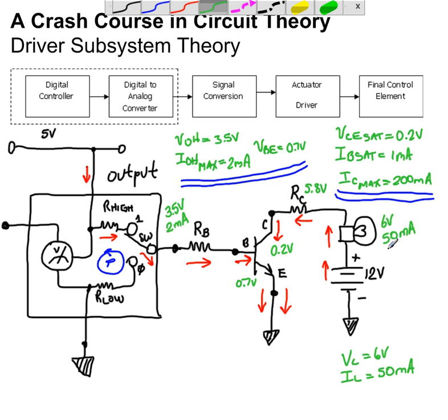Since we desire 50 milliamps to flow through this series circuit, the same current that comes out of the power supply or the energy source will be the same current that goes through this series network, which means 50 milliamps will be flowing through the collector resistor. Using Ohm's law, we are able to calculate the unknown value for RC. So we've completed the design for the collector circuit.